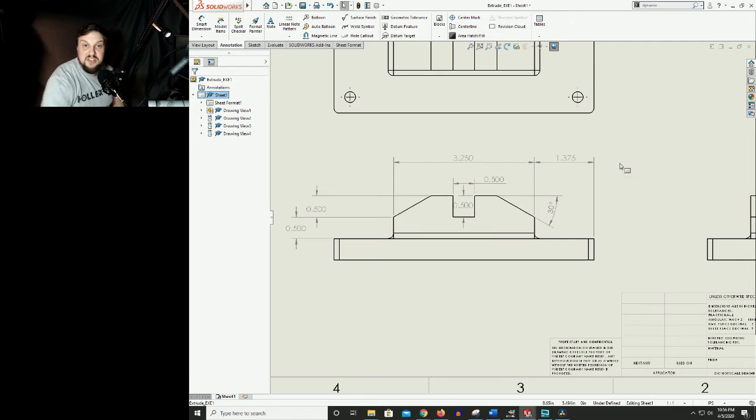Okay. And this is one of the reasons that we do drawings. And in all engineering applications, you do what's called a drawing check. So when you finish this thing off, you're going to hand it off to somebody else, and they're going to check it, make sure that it's right. So you do always have that checks and balance. If there's a place that's trying to get you to go around that, but they have the ability to do it, try to push back. It's always a better idea to always have your stuff checked.